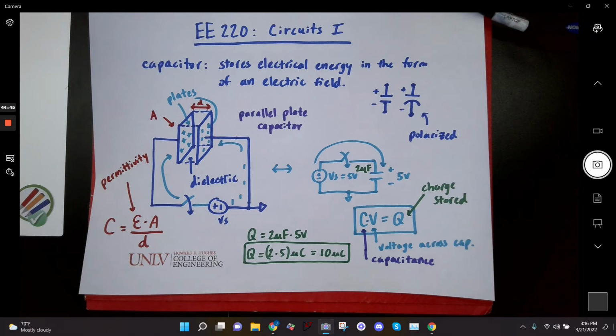Yeah. Half-life to capacitors, where they'll lose charge. Okay, so that's called leakage, and it also depends on where they're connected. If you just charge a capacitor and then set it aside somewhere and it's not connected to anything, theoretically it shouldn't lose its charge. It will stay charged until something touches it. But in systems, like on an integrated circuit or a circuit board, everything's connected to something, right? The capacitor might be disconnected electrically, but it's still connected to the circuit board, so you'll get some leakage into the circuit board. And it happens in memory too.